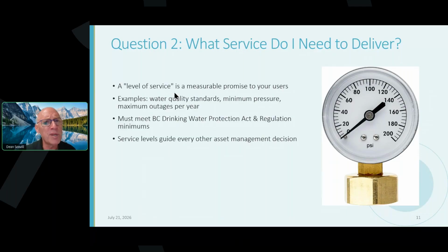I should maintain a minimum pressure too. Why is that important? Because if pressure falls below 20 psi, I've got a problem. With any potential leaks in my lines or potential cross connections from a customer, I can draw contamination into my lines.